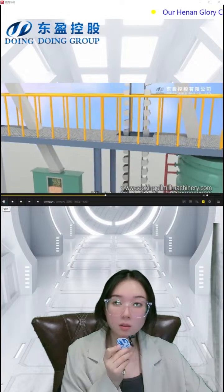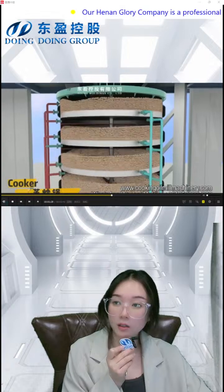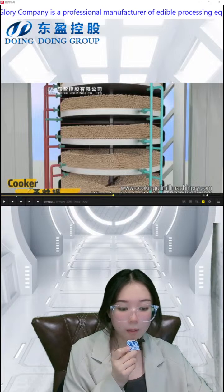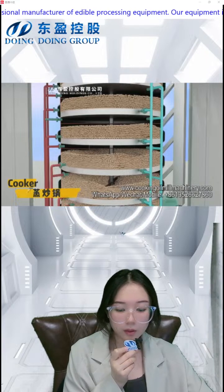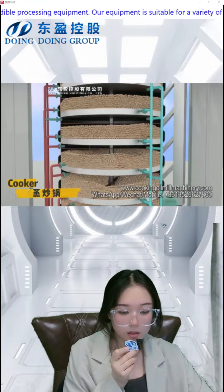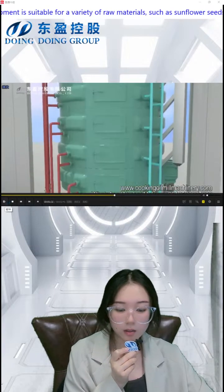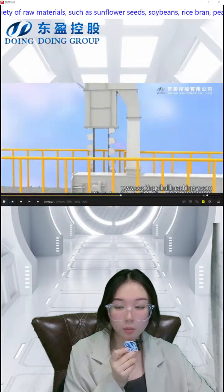And the next machine is a cooker. Through the bucket elevator, we adjust the moisture and the temperature of the oil seeds. Typically, the optimal processing temperature is around 100 degrees, and the moisture content is approximately 12%. It is fast heating, simple, and convenient to adjust the moisture.